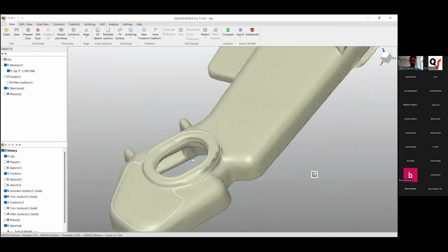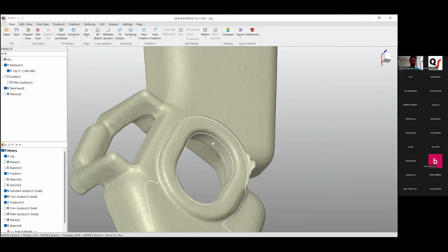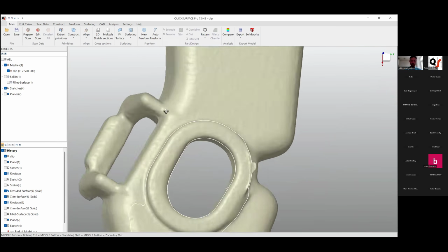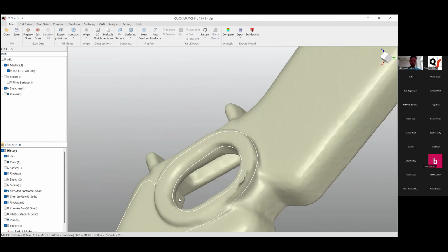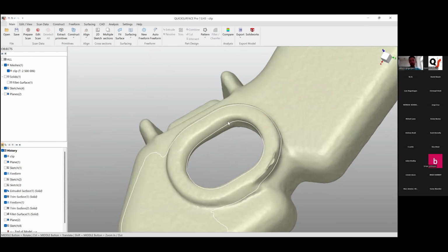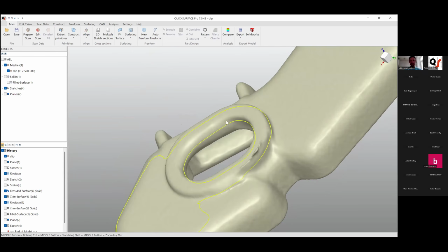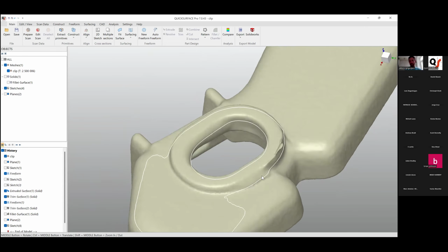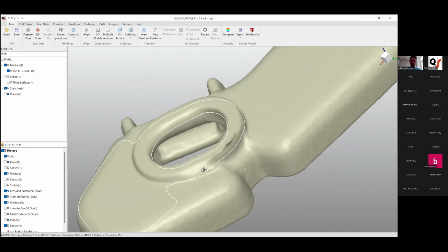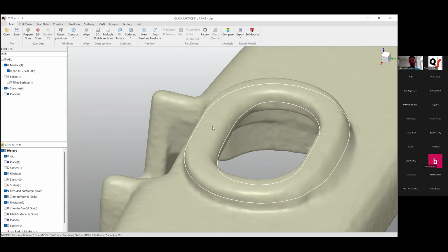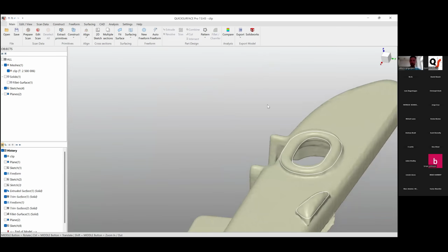And I want to explain one thing. Here we can see on this scan data that we have perfect vertical surfaces on this side, and on this side it's a bulge. So most likely there was some issue while scanning, and we had some missing scan points, so it just filled the holes with some kind of surface, and in this case it's a bulge, same as we see on this side, and same we have here. One side is nice and square, and this side is a bulge on this side as well.